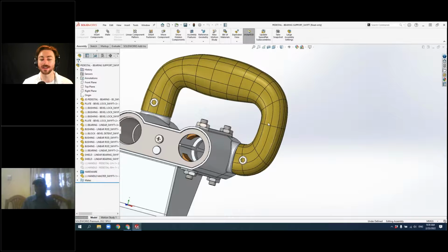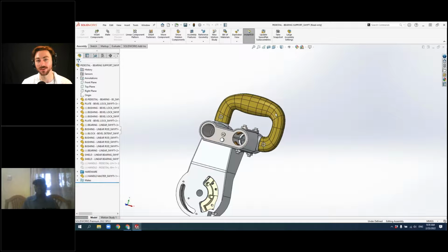So even though it's not necessarily in SOLIDWORKS, you can still work with SOLIDWORKS with this tool, and you can insert it as a derived component into a SOLIDWORKS part, and then carry on further operations downstream from that, like shelling it out, adding ribs, adding any kind of manufacturable features. And then if you update it, it's kind of like a master modeling technique: you update it upstream, all of those changes are going to carry on downstream. So there's a lot of flexibility in how you can use these tools. And like I said, this tool specifically is included with the 3DEXPERIENCE SOLIDWORKS offer, but there's a wide range of design tools that you can expand your capabilities with.